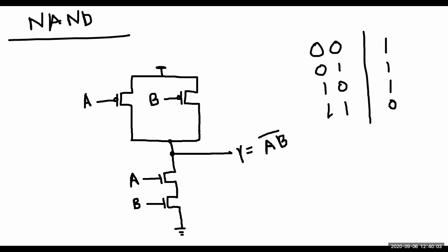Almost like this one, right? Opposite, sir. Opposite. How can you say that opposite? What is the opposite thing? Opposite of NAND gate. I think NMOS will be on top, sir. NMOS will be on top? No. Remember, you are going well, but your NMOS will never be on top. Your PMOS will never be on the bottom. Think again. You are on the right track. Think again. Sir, maybe the PMOS will be in series.